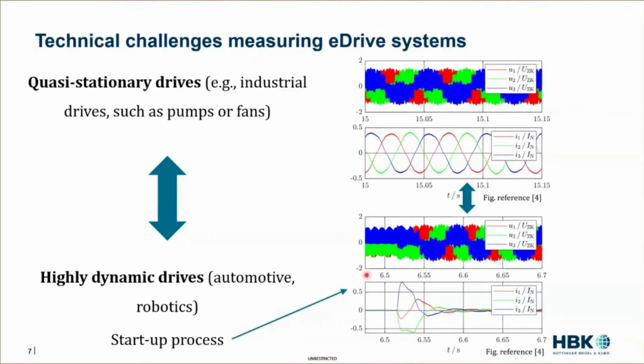And what we can also provide, this is also a part of a development in cooperation with Aschaffenburg University, we developed a highly dynamic power analysis method, which can also be used to analyze those signals. And it is not linked to the fundamental cycle of the signals, it's linked to the switching cycle of the inverter. And therefore, the power quantities can be calculated with a drastically increased update rate.